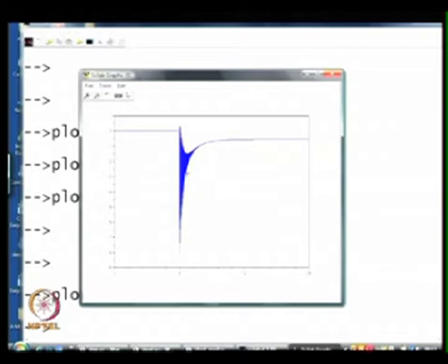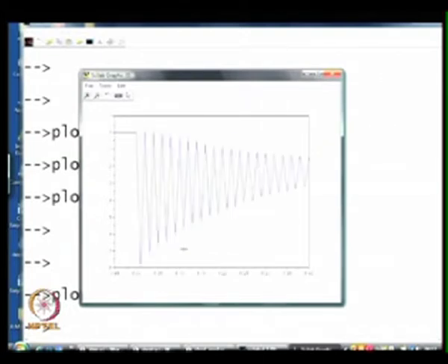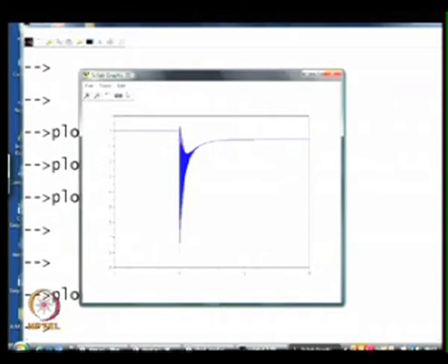Okay, so what you notice of course is the response consists of several modes. Some of the modes are not very clearly seen, but one of the dramatic things you see is that there is an oscillation. This is not surprising because one of our eigenvalues is a complex eigenvalue with an imaginary part equal to omega, in fact 313, you recall that eigenvalue? Yeah, so this is what is manifest here. You also see that there seems to be some kind of an exponential decay.